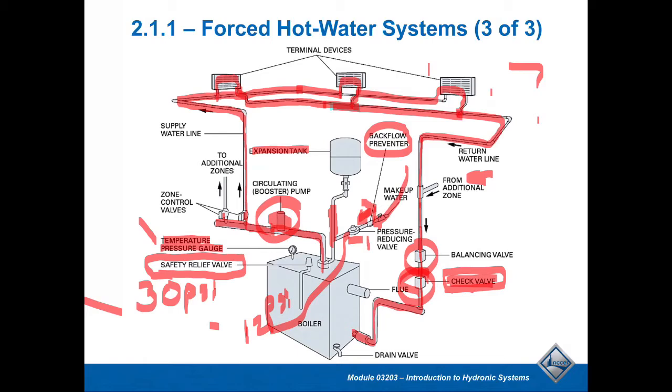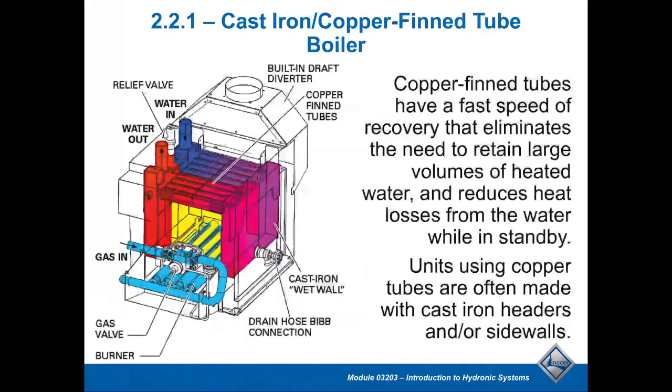The expansion tank in this application is intended to allow for the safe expansion of the water as the boiler system is warming up, as the boiler is adding heat to this. We need to allow for that expansion. So a lot of the current tanks have a bladder in this system. As that water expands, it takes an air cushion on this side and pushes that diaphragm directly towards that air and compresses it. And that's typical of anything that we would put in today.